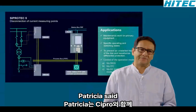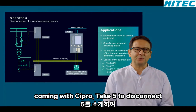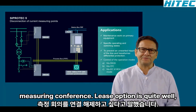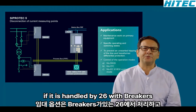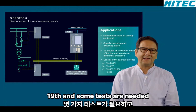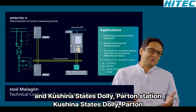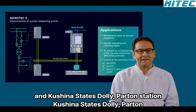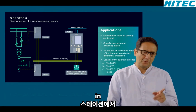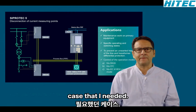At first step, I would like to introduce the option coming with SIPROTEC 5 to disconnect measuring current points. This option is quite useful when the feeder is handled by 2 circuit breakers and one of them goes to maintenance, and some tests are needed, or in case of some specific operation and switching states that are required in the station. Here in the slide, I have an application with transformer differential protection, where the high voltage side is having 2 measuring points for the side 1.